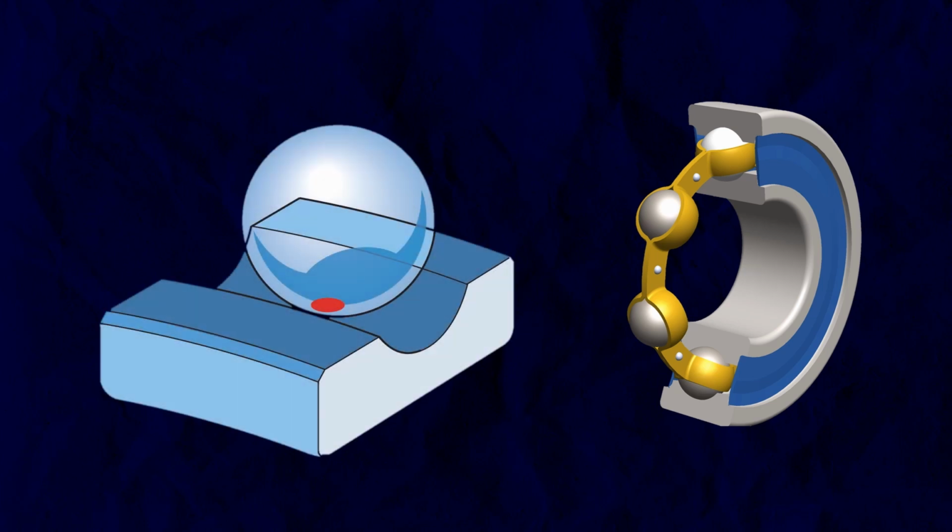Here the deep groove ball bearing has point contact, and to be exact, it's actually not a sharp point contact. In operating conditions, balls make a tiny circular contact because of tiny deformation of the ball under loading. But the fact is ball bearings can provide high speed among all types of rolling bearings because the balls make the smallest contact and produce the lowest amount of heat at high speed. So the thermal limitation of the ball bearing is high.